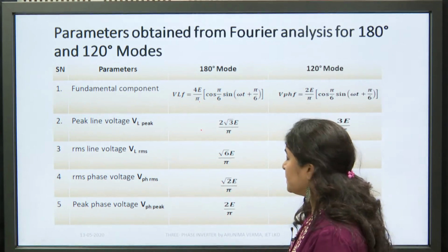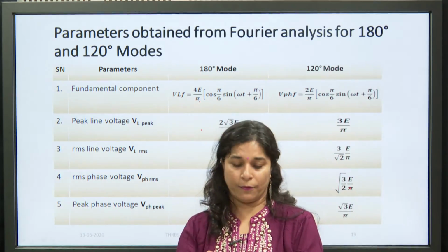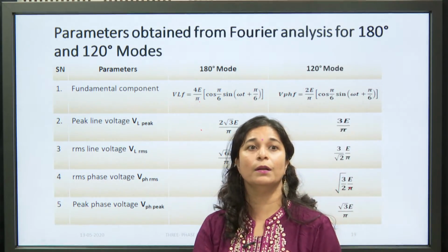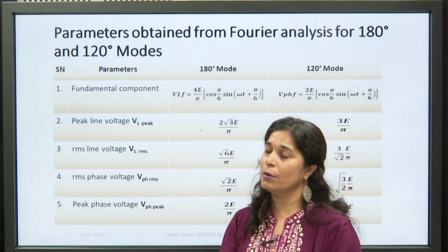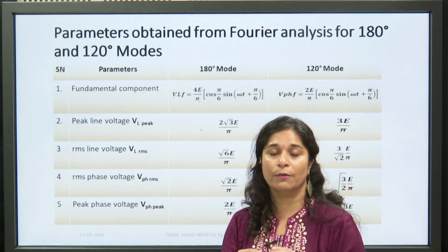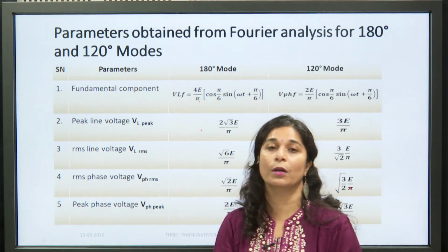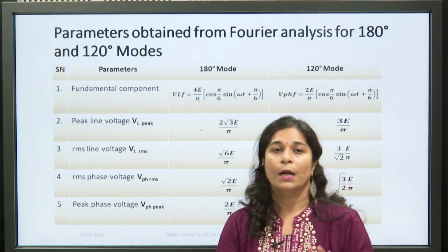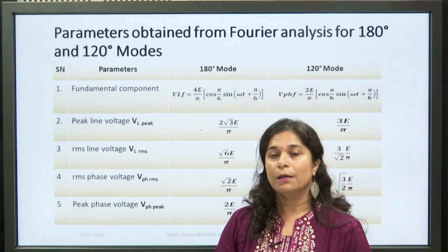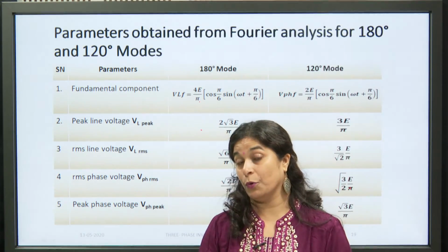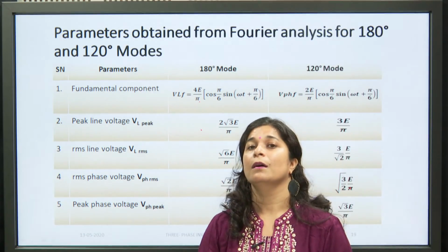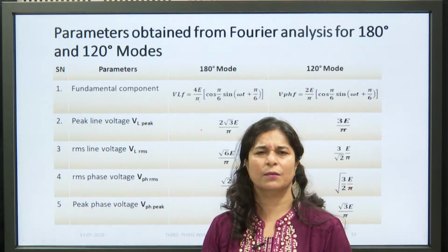Now, in this case, according to the desired speed, you have to have the equivalent voltage available at the input of the motor, which is obviously the output of the inverter, and this requires different voltage levels for different speed operation in different industrial and commercial applications.